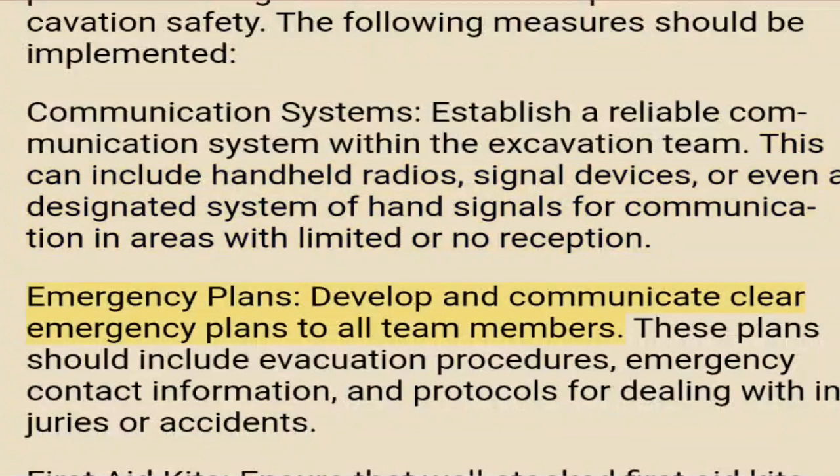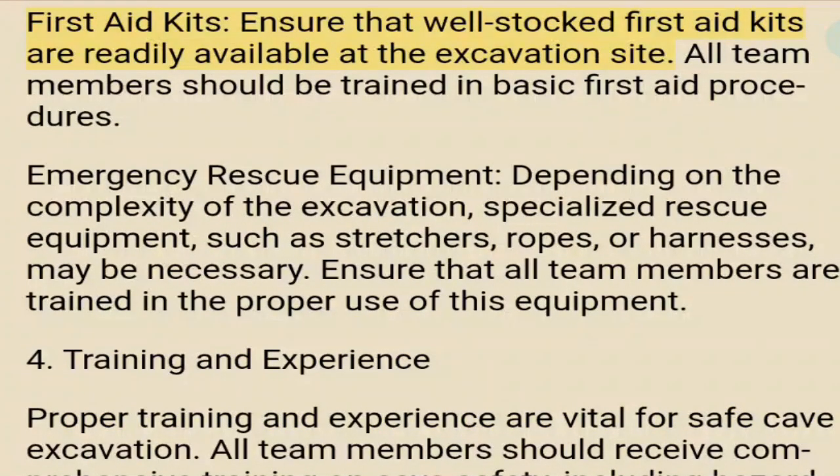Emergency plans. Develop and communicate clear emergency plans to all team members. These plans should include evacuation procedures, emergency contact information, and protocols for dealing with injuries or accidents. First aid kits. Ensure that well-stocked first aid kits are readily available at the excavation site. All team members should be trained in basic first aid procedures. Emergency rescue equipment. Depending on the complexity of the excavation, specialized rescue equipment, such as stretchers, ropes, or harnesses, may be necessary. Ensure that all team members are trained in the proper use of this equipment.